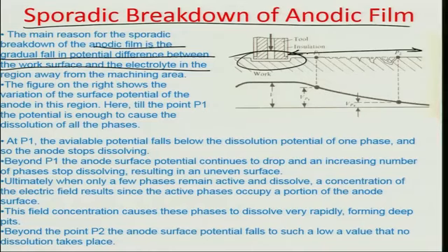Obviously, as you know, the electric field between the tool and the workpiece would fall as a function of the square of the distance as it goes from this particular point onwards, and therefore the field available here or here or here would vary quite a bit, and would be lesser and lesser as we go ahead. You have to remember that there is electrolyte flow in this region. The electrolyte is traveling all the way over this work surface into these regions, and you can say that a field is being created between the tool and work by virtue of the electrolyte flow over these regions.